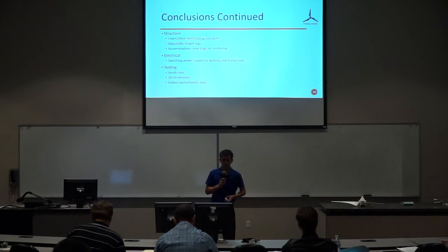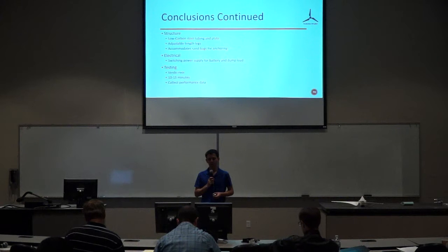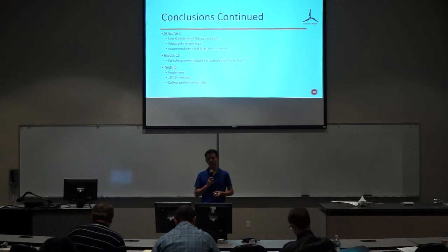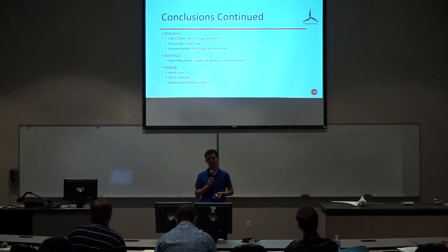For the structure, we will utilize low carbon steel tubing and plates that we will paint. Due to the short duration of our test, we do not anticipate any corrosion or problems with that material. We will have adjustable length legs to increase the amount of deployment areas that we can utilize for our test. And the structure also accommodates sandbags for anchoring so that it is more secure for our test.